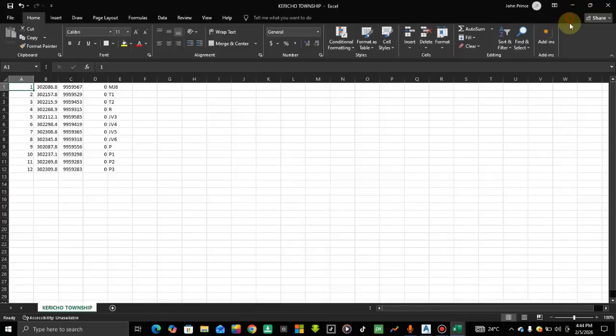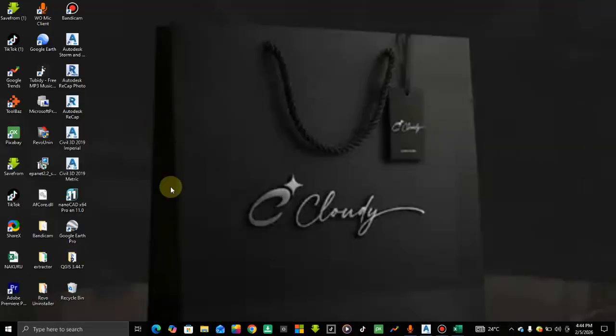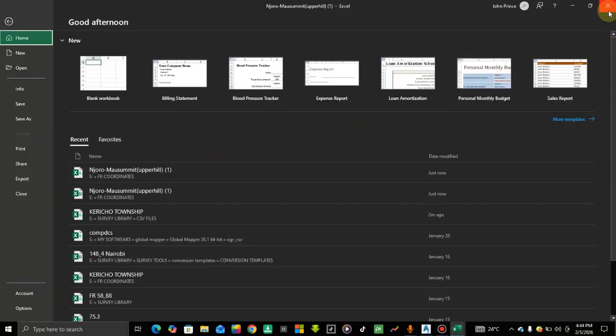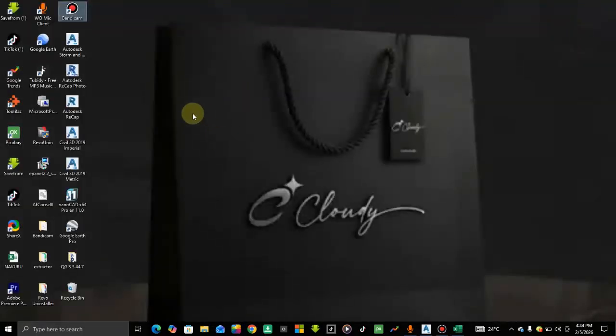Now, another option. Remember we are just doing a basic introduction. I know you have come across some of these things. Maybe you found out that your Excel is not working. So are you going to stop working as a civil engineer? Absolutely no. Civil engineers and surveyors must keep on working day in, day out. So what are you going to do? We have another file type format that can be manipulated into the Civil 3D, and that file format is called the text document space delimited.